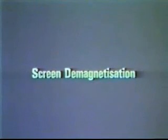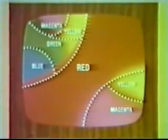A color picture tube is very sensitive to magnetic effects, due either to local or the Earth's magnetic field, and it may easily become permanently magnetized. Adjustments should be made with the receiver in the position in which it is intended to be used. This effect can most easily be seen when displaying a single color raster. A magnetized tube is incapable of giving a proper color picture, and it is necessary, therefore, to demagnetize it.